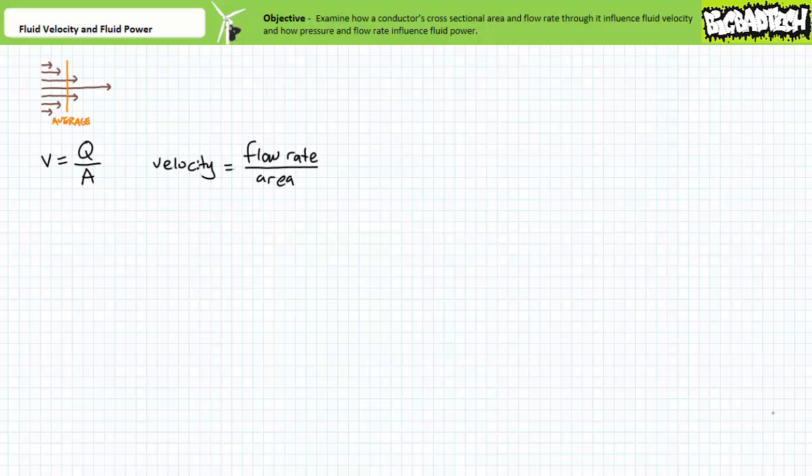At first glance, this formula may seem self-evident, but I must caution you that details, notably units, are extremely important considerations. A cursory analysis of this relationship suggests that when flow rate is held constant, and we increase the cross-sectional area, the velocity decreases. This makes perfect sense. Consider a tunnel full of commuters on their way to a subway. Given 100 people per minute entering a super wide tunnel, people in the tunnel can take their time and stroll quite leisurely given the tunnel is wide enough to accommodate this quantity of people per minute.